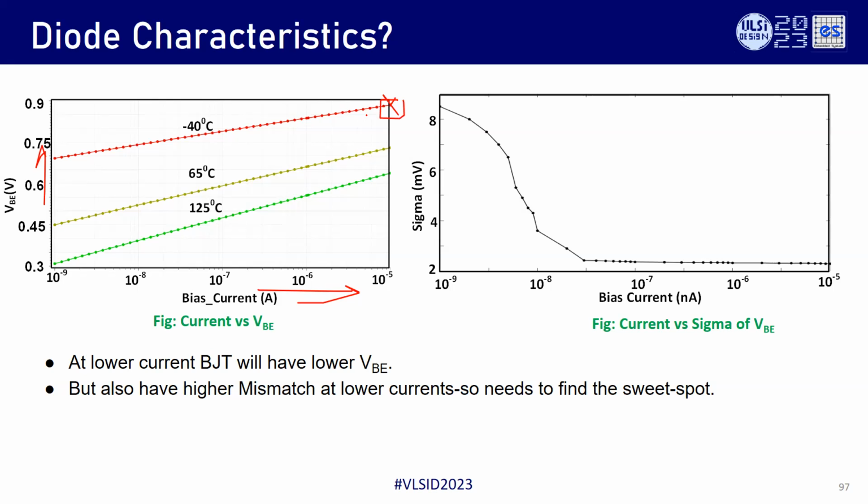So that limits the bias. By looking at this one, we know that at any point we cannot bias this to less than 950, because we need to leave another 50-60 millivolts in the worst case for the PMOS current sources. So now, how to minimize this?